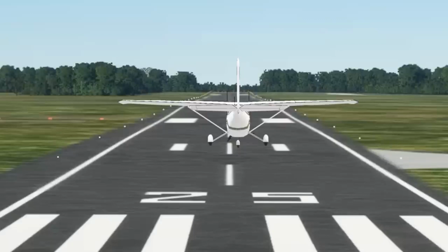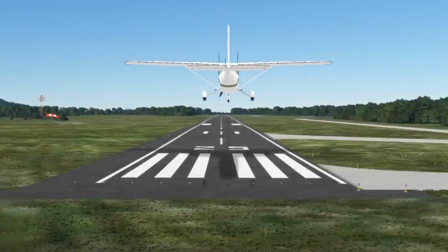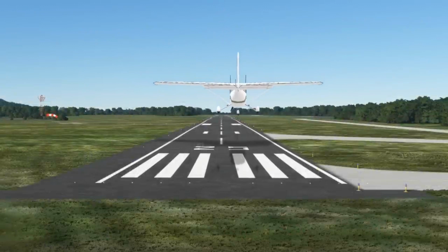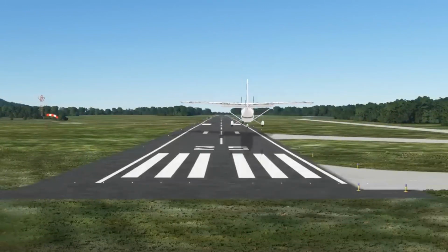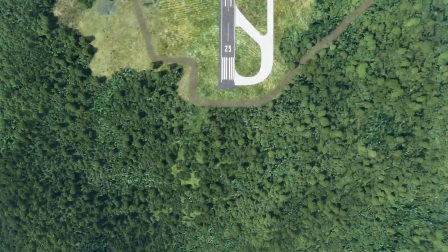Characteristically, an airplane has a greater profile or side area behind the main landing gear than forward of the gear. With the main wheels acting as a pivot point and the greater surface area exposed to the crosswind behind that pivot point, the airplane tends to turn or weathervane into the wind.